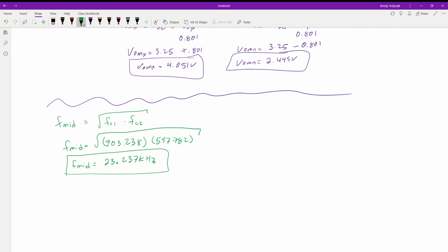Now the assumptions we have: we're right smack dab in the middle of where this is operating. So neither C1 is going to be a short, nor C2 an open right off the bat. We have to figure out and determine what's going on. So again, we're going to redraw our AC circuit. We've got C2, R2, R3, R1, Rgen, Vgen.